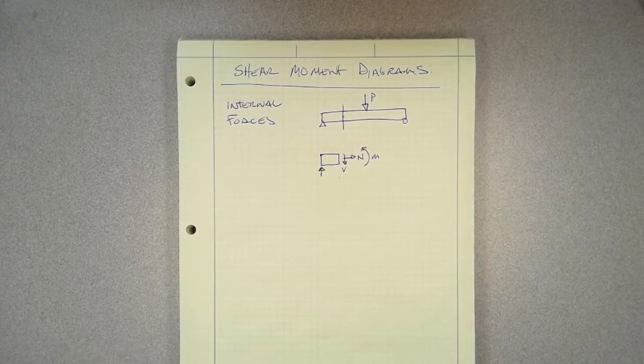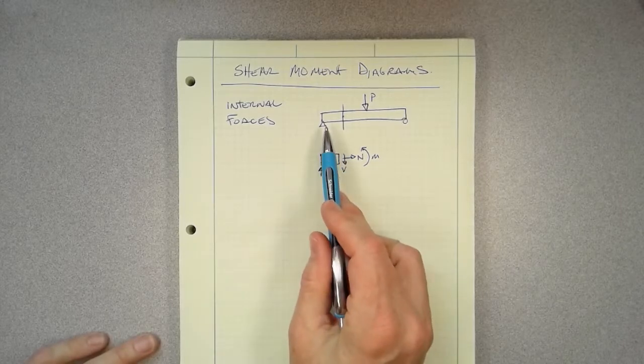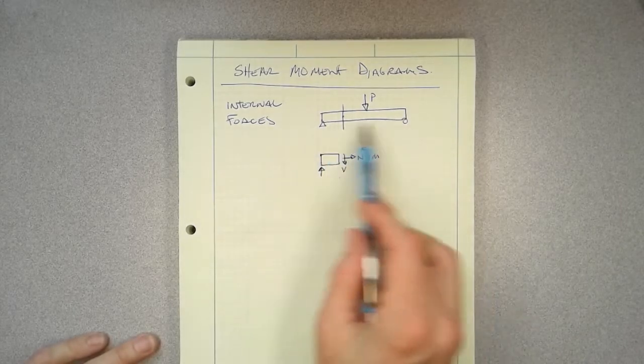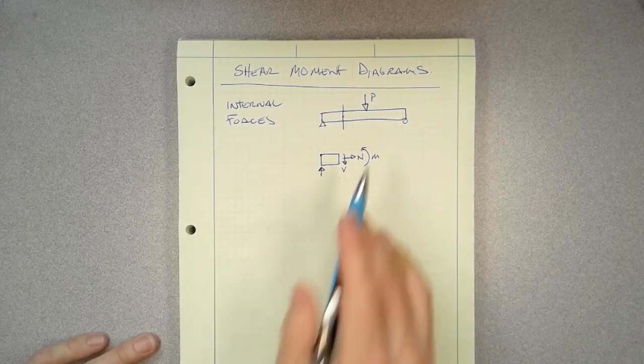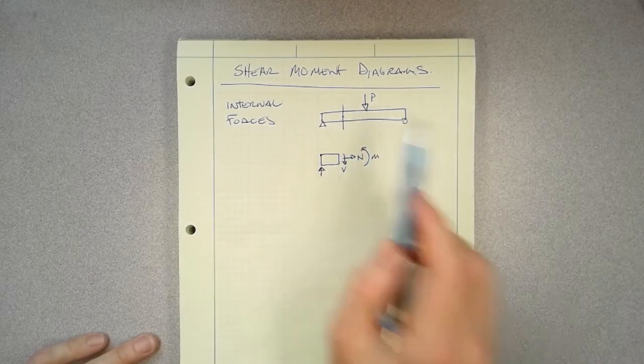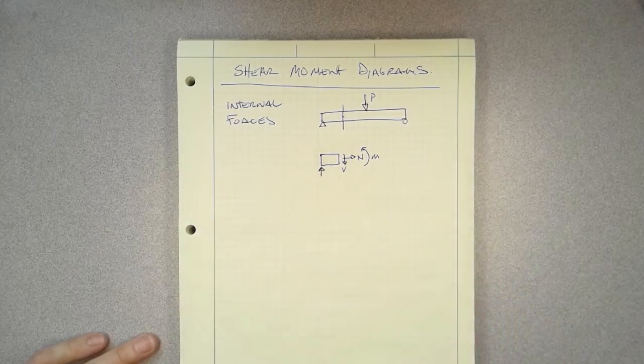Now, for the guidance when we break up our beam, I'm going to use this for our example. This is a simply supported beam with a concentrated load, which I'm going to place right in the middle of the beam. What we're looking for is to break it up into sections where we have point loads or point reactions. Basically, point loads or forces. That could be a reaction, or that could be an applied load. Those are going to be the boundaries of our sections.